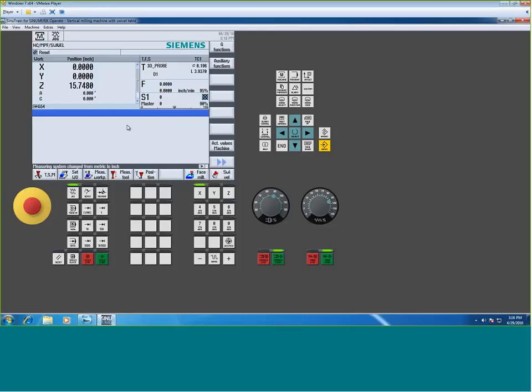So a couple of things I have to do. When I'm calibrating the physical probe, I want to go to Measure Workpiece, and I want to go to the Calibrate function. You have to calibrate a probe in two things, length and radius. The radius one's pretty simple. You just go to radius, you give it a quote-unquote ring diameter, call it whatever you want. Wherever she sits, hit cycle start, it'll run through, and now it's calibrated via the radius. It's very, very simple. The tricky one is the length.